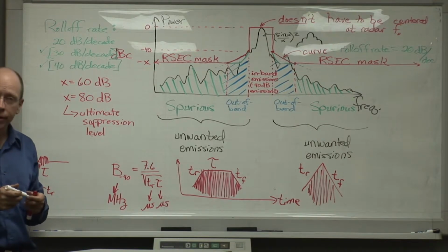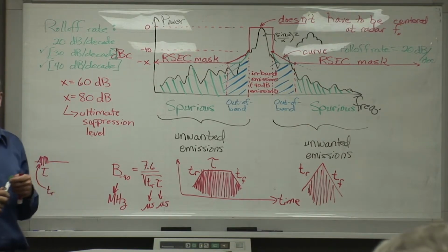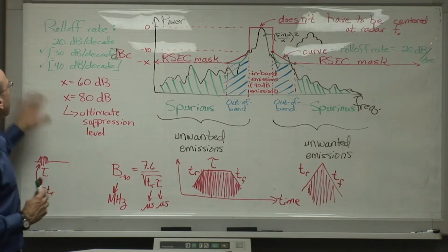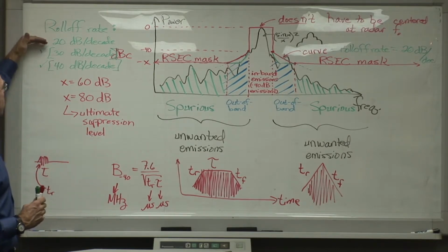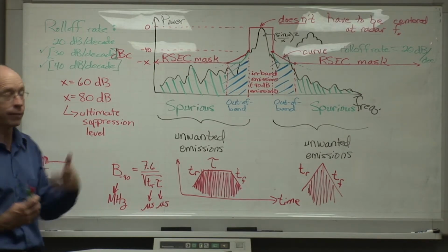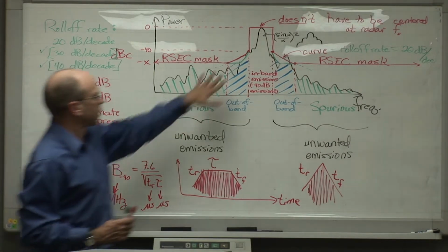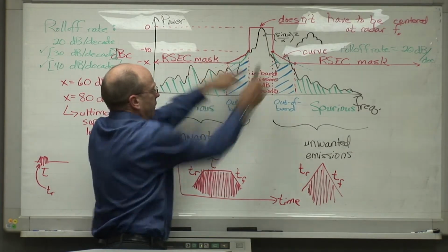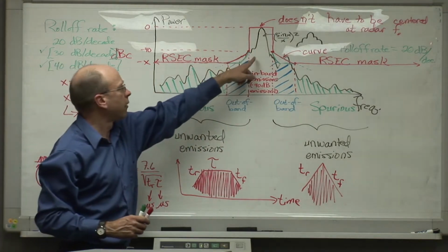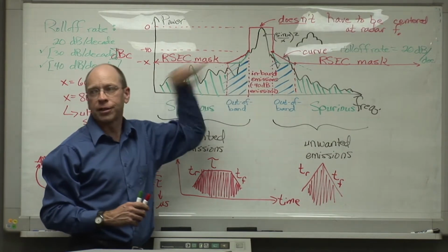And at the time that I'm giving this talk, NTIA, working in concert with other agencies in the U.S. Interdepartment Radio Advisory Committee, is in fact discussing whether or not we need to move from 20 dB per decade to either 30 or 40 dB per decade for various types of radars. The bottom line is that the shape remains the same. It's just a question of how sharply we feel that we can roll that down. And this really depends upon how good we think these radars are that are operating as part of the spectrum.